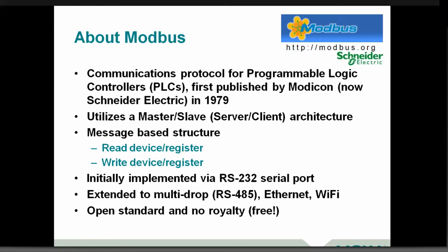As a quick review, Modbus uses a master-slave or client-server architecture, which fits well for most SCADA and data monitoring collection applications, with a register-based read-write architecture. While it started out with serial ports, it was rapidly adopted for a lot of things.